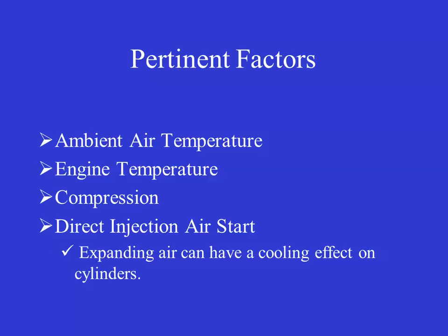Compression. If your engine has low compression pressures, again, your temperatures and pressures in the cylinder may not be high enough to ignite the incoming fuel air charge. Direct injection air start, which is very common on all your larger engines. As you're injecting air into the cylinder, it's expanding, and that can have a cooling effect on the cylinders, which will also affect this.